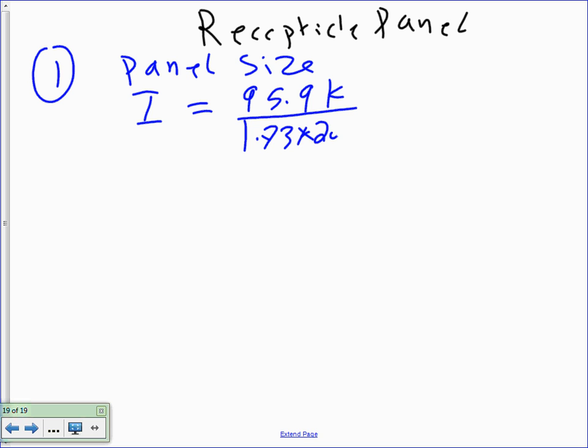1.73 times 208. I need one very competent young fella, or not so young fella, to give me the answer. What's the amp? Where are the A students? Did they go home today? Brian's not here. Okay, come on. 95.9 divided by 1.73 divided by 208 is 266.5. 267. 267 is okay? Cool, thank you.